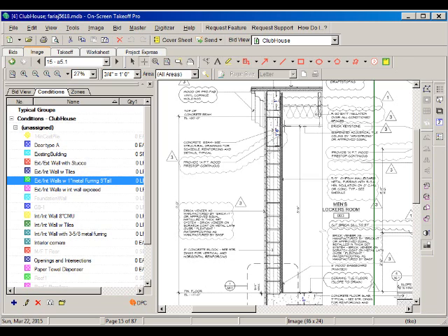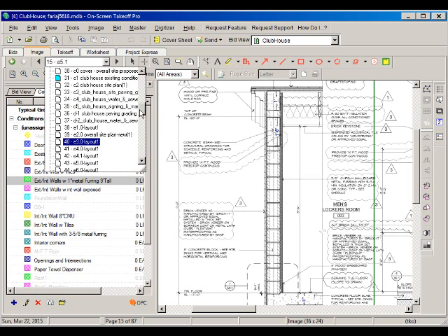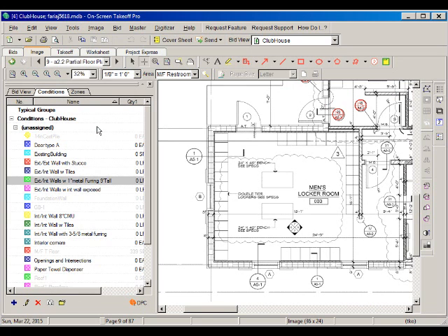Instead of using maybe a 5 or 8% waste factor, they may be using 3% because they're including that small section. It depends really on the estimator. So let's go back to our drawing, the plan layout drawing A22, and we're going to make sure that we have the area as unassigned, because if not, if we have it in a typical area, we will be counting these sections several times.